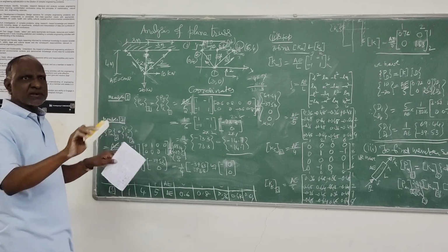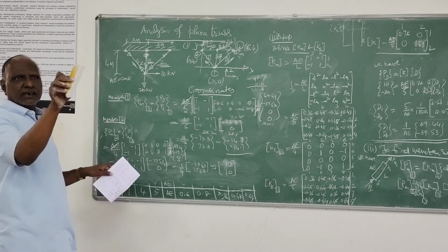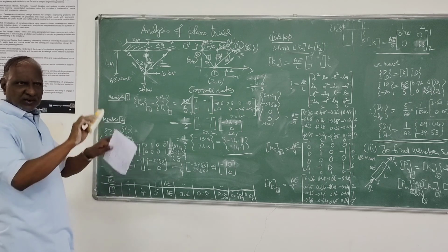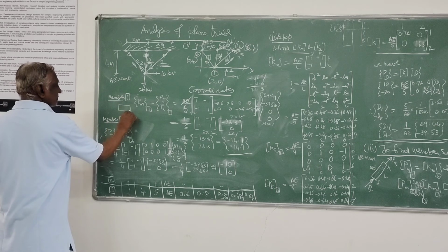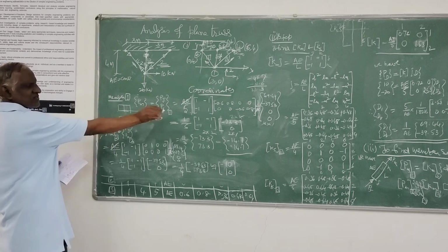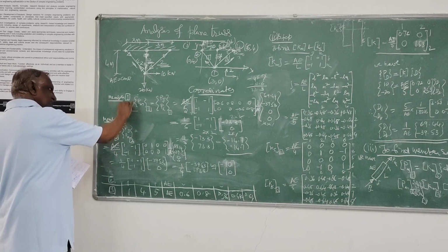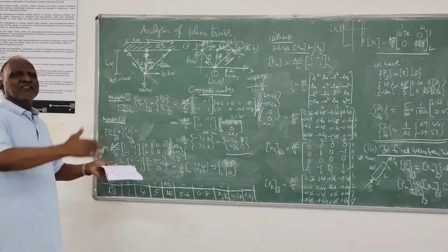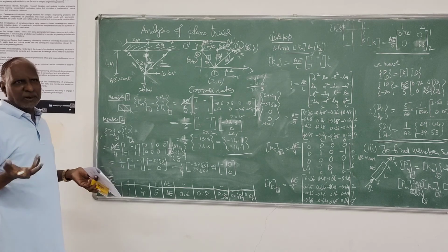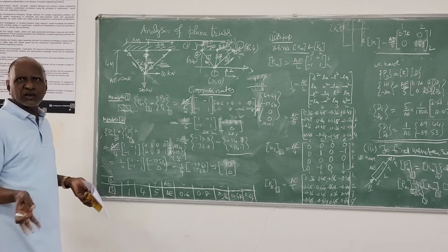Hinge on plate zone is stable. If that rectangle or square arrangement zone is stable. So arrangements cannot be just like this. This sort of truss you don't get. Always you should have triangles only. When you have triangle, you have an inclined member. Inclined member only you have to have.